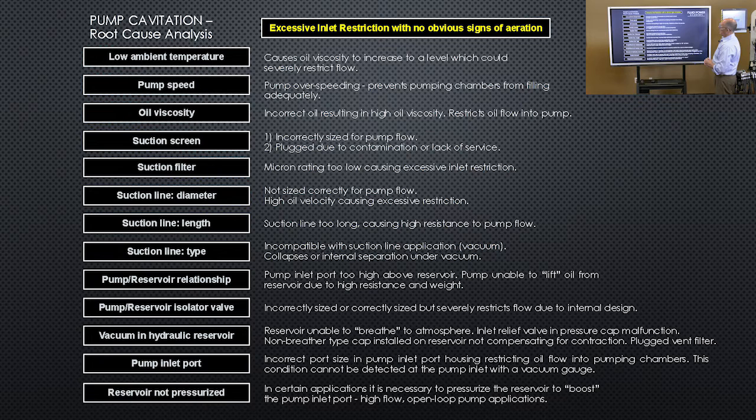The following is a list of the most common reasons why we would have cavitation. First of all, low ambient temperature, pump overspeed condition, oil viscosity, the incorrect oil, or the oil's too cold. Suction screen, maybe partially plugged or undersized. Suction filter, the same problem. Suction line diameter, that's an inherent design problem, for example. It's not the right diameter, it's too long, or it's the wrong type.